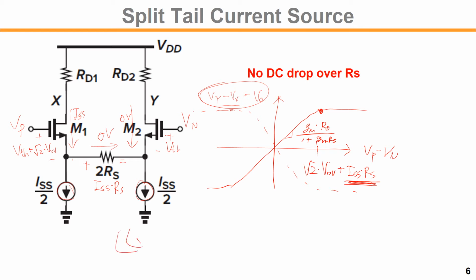From the undergraduate course, we learned that such a single-ended amplifier would have Rs, because at the middle the voltage would be AC ground, since there is no voltage variation. The voltage goes up and down by the same amount if we assume the linearized small signal model. Okay, so this is AC ground, so we can find that equivalent small signal model.